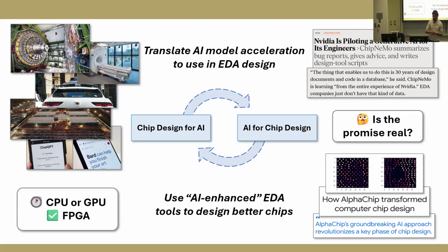Let's say you're talking about using reinforcement learning during ASIC detailed placement, right? They have metrics like half perimeter wire length to measure the quality of results of that specific step. But at that level, there's also LLMs for generating Verilog, right? And then at that level, it's more about: is the syntax correct? There are pass rates. Is the functionality correct? So you can measure how good it is at that level of granularity.